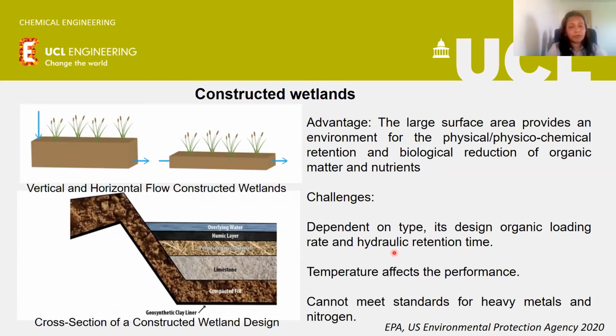As I said before, it depends on the design. It depends on the hydraulic loading and the retention time as the water infiltrates through the different layers. And it cannot meet the standards we expect for heavy metals and nitrogen. So that's where research comes into play. How do we improve this?